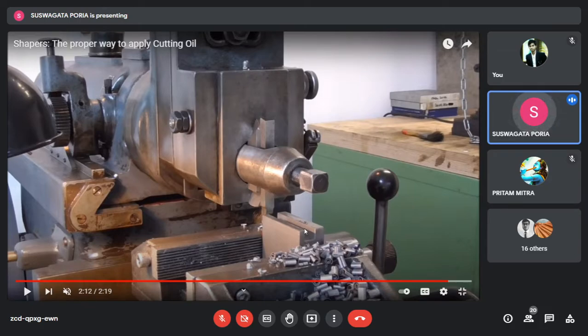So when it is going backward, the tool is getting a force from the workpiece in the forward direction. That's why it is being lifted. But when it reaches its original position and starts to cut, a backward force is also applied there. So it should go backward, but it is not possible because there is a flat plate which is resisting its backward movement. So this plate can only come forward, only lift up, but can't move in the backward direction. Okay. So this mechanism is called the clapper box.